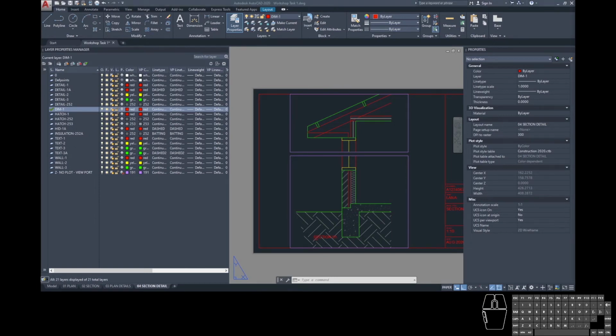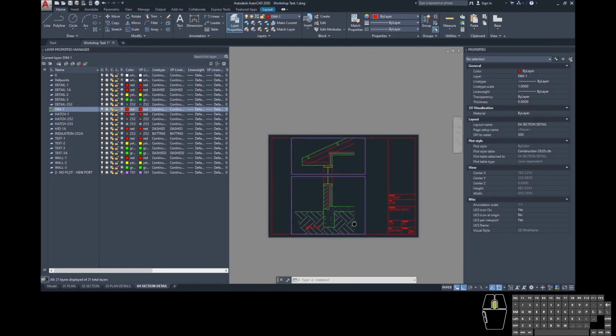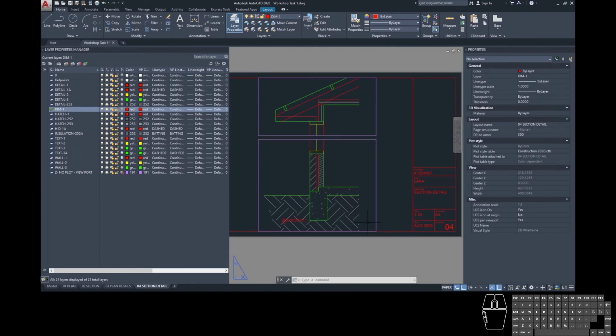You'll now be able to fill out the rest of the detail for all of these in model space, and then come into paper space and annotate them using multi-leaders, making sure you're lining them up in nice columns, setting out everything nice and neat. But you've got all of those tools to be able to do that now. You have all of those skills.